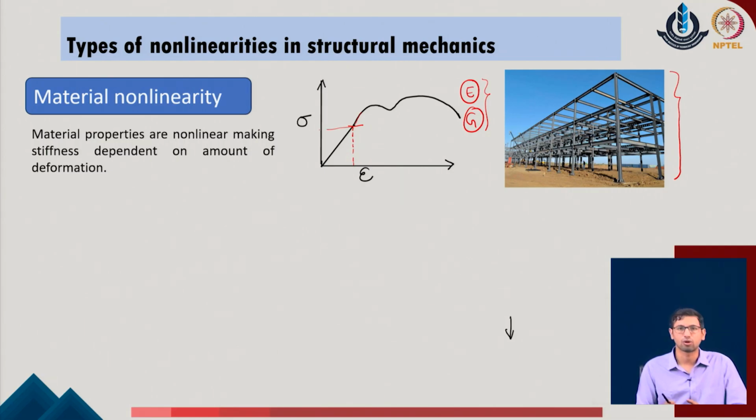The material can also take a very good amount of load beyond the standard proportionality limit. So, if we want to utilize the material beyond this part, which is significantly more, then we have to adopt the nonlinear material response in the given system. And as we consider the material response to be nonlinear, the structural analysis for the system should also incorporate that in the regular stiffness evaluation of the given system.